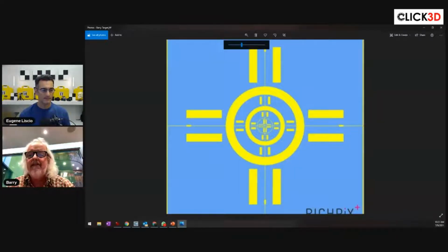The critical thing in photogrammetry is the accuracy of your control. I mean, there's lots of things out there that will help you stitch, but you've still got to get scale and you've got to get control in. I just find these targets useful.